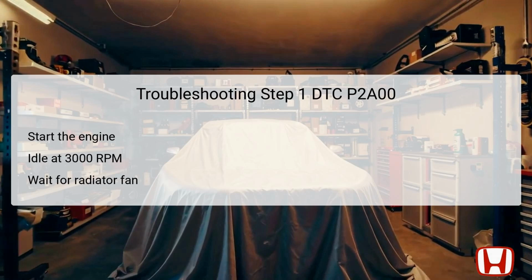Hold this engine speed until the radiator fan activates, indicating that the engine is reaching an appropriate operating temperature. This initial phase is vital for setting the stage for the following diagnostic steps, as the engine needs to be in the right condition for accurate sensor readings and diagnosis. Once this is confirmed, you can then proceed to the next phase of diagnostics to pinpoint the issue further.